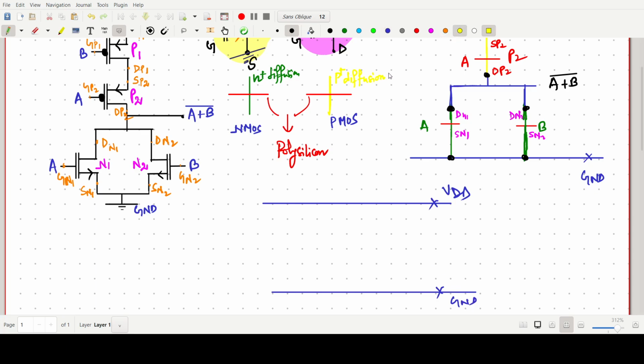Then after, we have to make two PMOS. Okay, you see this kind of thing. So for two PMOS, directly take one big line, then two lines A and B. Clear. And then one green line, two green lines for NMOS. The source terminal is connected to ground, so make it ground. Then you can choose one metal line.